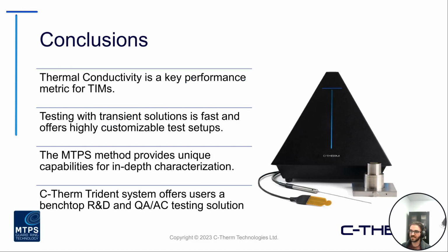So just getting close to the end here, but as some conclusions, just what we've talked about here today so far. Thermal conductivity is often seen as a key performance metric for these materials. Testing with transient solutions is going to be faster compared to your traditional steady state, and typically offers highly customizable test setups, again, whether that's pressure, temperature, humidity, saturation, things like this.